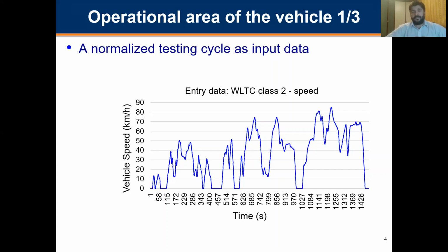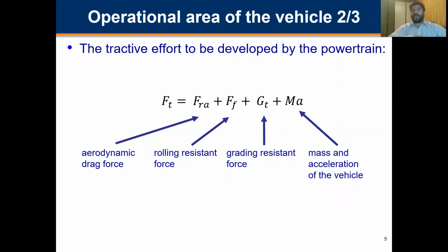From this we have the speed evolution at different moments of time during the testing cycle. From this speed, we are able to calculate the acceleration and the tractive effort to be developed by the powertrain. From the vehicle characteristics, we are also able to make this calculation.